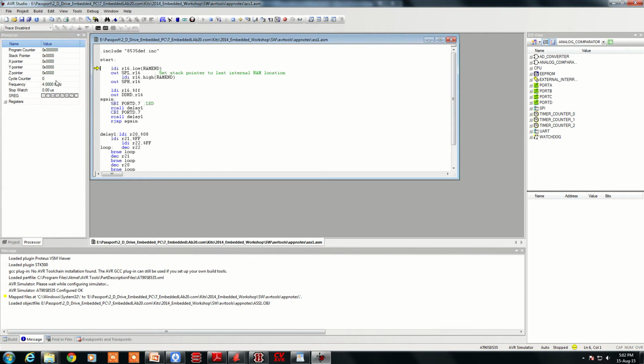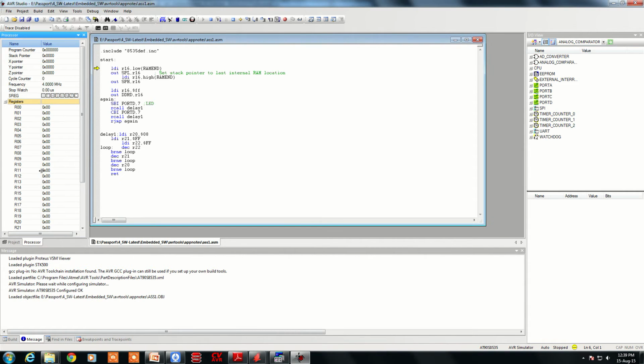Now you will see that on the left side the CPU registers are open, on the right side the CPU peripherals are open, and your assembly language is displayed over here with the cursor highlighted. So if you miss any one of these steps, then the screen will be blank. And the register windows. On the right side it will show the CPU peripherals like ports, timers, ADC, and the UART.